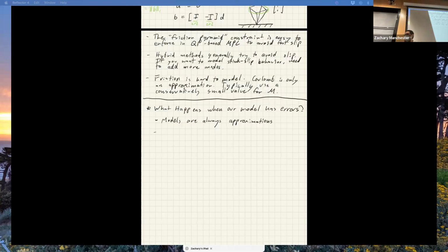Building on that, simpler models are often preferred in control, even if they're less accurate. In principle, we could write down super accurate physics models that model everything really well, but practically, those more complicated, more nonlinear models are really unwieldy and hard to deal with. So usually in control, if we can get away with it, we use linear models because they're really easy to work with.